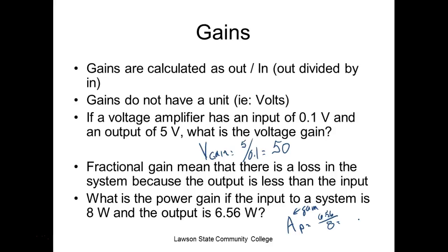We call it a gain though. The gain formula does not mean you get more out than you put in. It's just a formula. So what would we get? 0.7. And what's the unit? No unit. Gain has no units, right? But here we don't actually have a true gain. We have a loss. Technically, we refer to losses as attenuation. But the gain formula doesn't change.